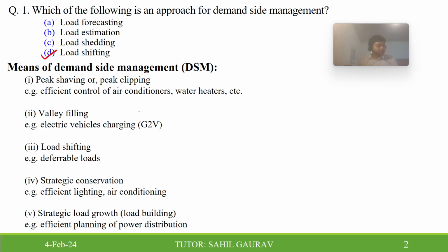The major point I want to write here is that we do demand side management to improve efficiency and cost effectiveness of energy usage on the customer side of the meter. In general, such control results in load reduction at time t. If you see peak saving or peak clipping, in this management strategy we have reduction in both peak demand and total energy consumption.